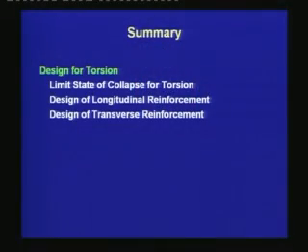Next, we moved on to the design of the transverse reinforcement, and there what we have found is that the area of transverse reinforcement is calculated based on two concepts. Whichever gives the higher value is selected. The first expression is based on the skew bending theory. The expression is related with the equivalent torsional moment MT, and from that we calculate one value of ASV.